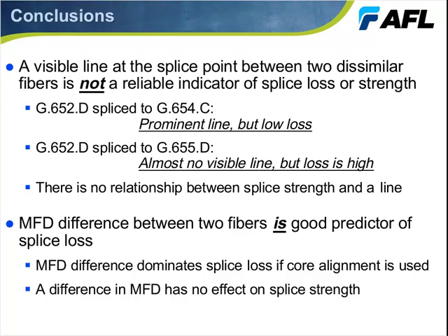Now, if we were going to talk about mechanical splicing, it's a completely different subject, because there we haven't really welded the glass together, and temperature effects or humidity or things can cause some variation of attenuation or in some cases even a dramatic failure.